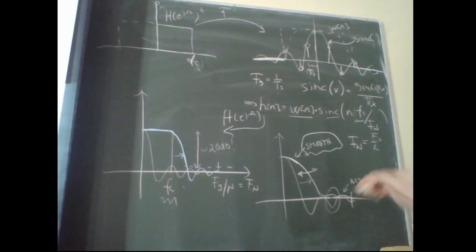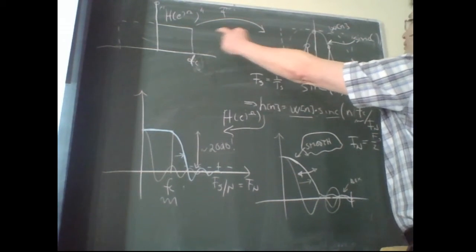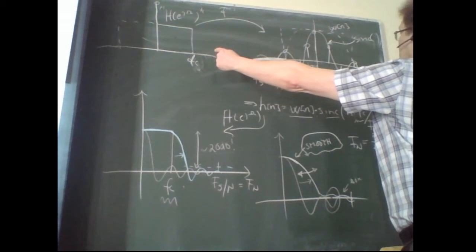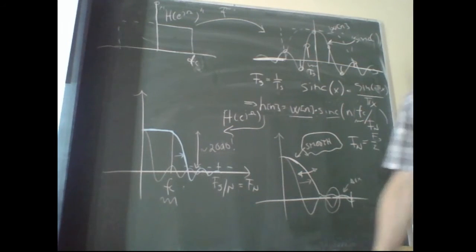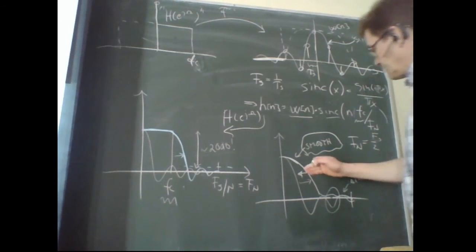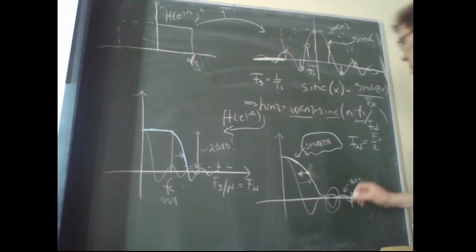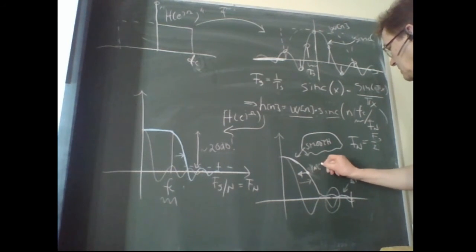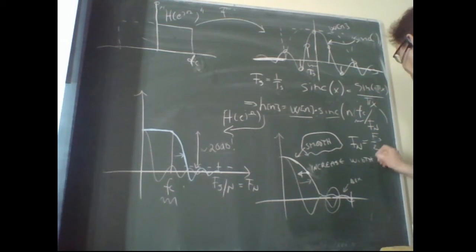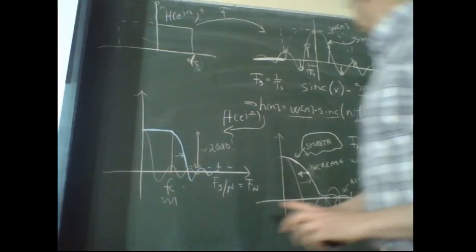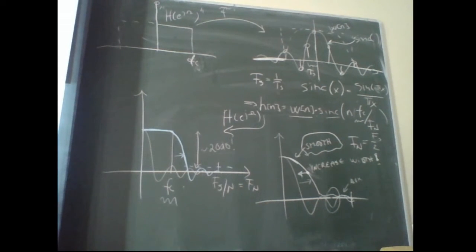So multiplication in time, meaning a wider sample of the sinc, would decrease the transition bandwidth. So to get a better transition bandwidth, increase the width. No magic there. Good. So that's how the window method on low-pass filter design would look.